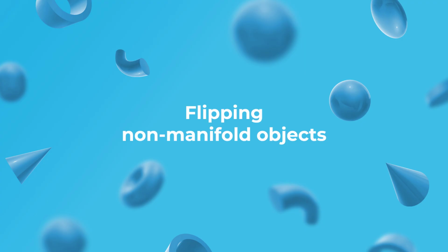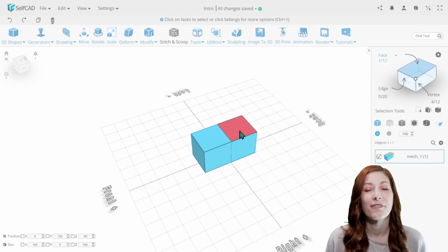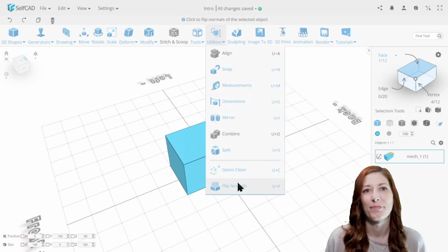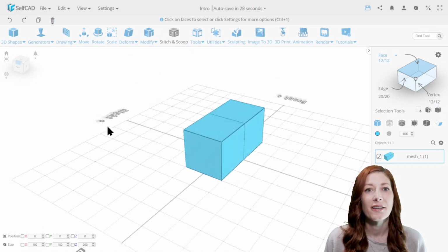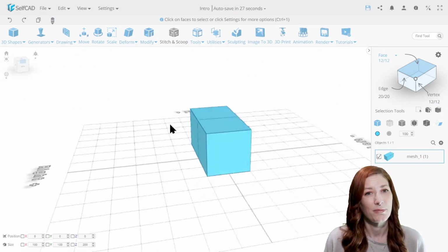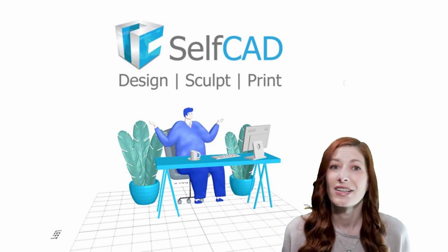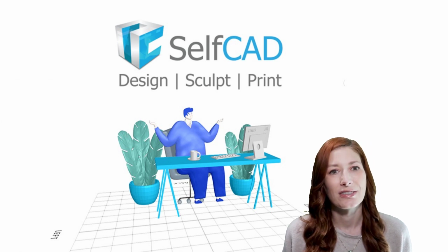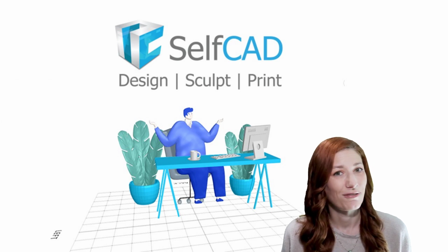Flipping non-manifold objects. The solution to that is to fix them manually by selecting the flipped faces first and only then using the Flip Normals tool. This way, you will circumvent the manifold requirement when using the Flip Normals on the entire object. However, correcting and fixing the face orientation is just the start, as non-manifold objects often have other issues that require fixing, which brings us to the next issue we need to check for.